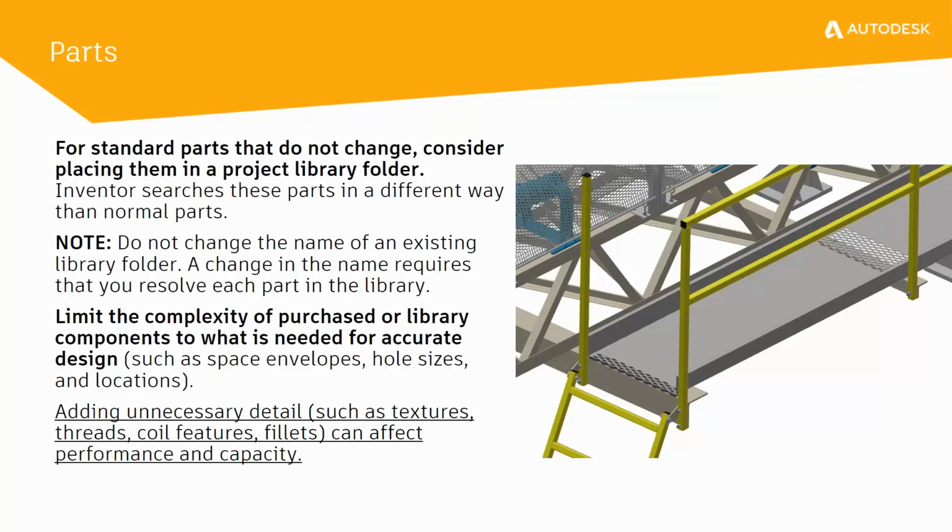The other thing is, in the guard, you'll see that though it actually looks like it's a modeled mesh, again, the reality is this is handled through an image that's giving a texture to the geometry that allows for perforation in our sheets. So again, the system has much better capacity for handling these types of products rather than products that do have all of the holes and all of the details modeled in them.